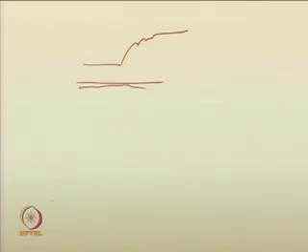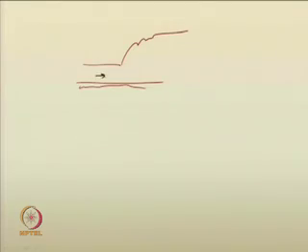Generally, for various hydraulic designs and hydraulic structures, you create hydraulic jumps so that the energy gets dissipated. So, what does the hydraulic jump do? How does it dissipate the energy? The incoming flow has higher velocity and the outgoing flow from the jump has lower velocity, so the kinetic energy is getting reduced.